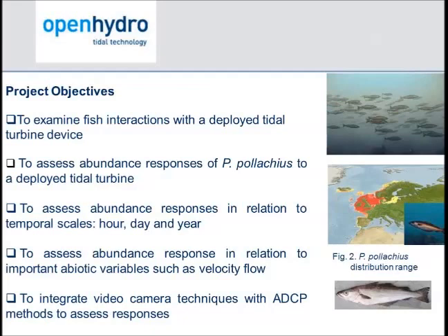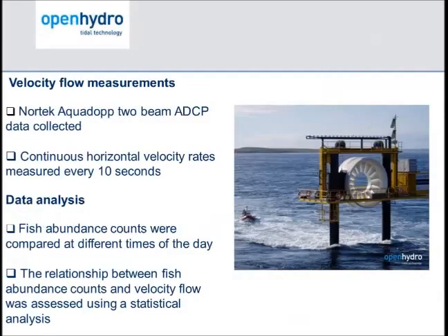So to do this, we were integrating the video camera technique with ADCPs, acoustic Doppler current profilers. So these are pieces of equipment that allow us to measure the velocity in water flows by looking at particulate matter. Next slide, please. So the velocity measurements, in order to understand both the performance of the turbine and also the fish behavior, we wanted really to use the ADCPs.